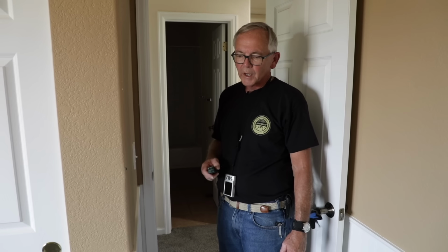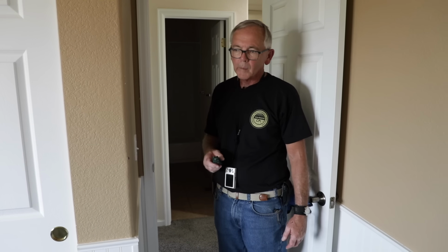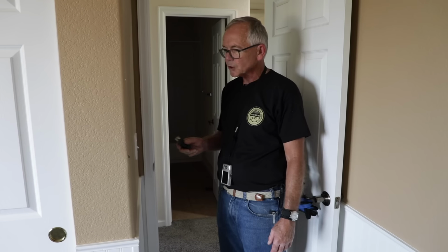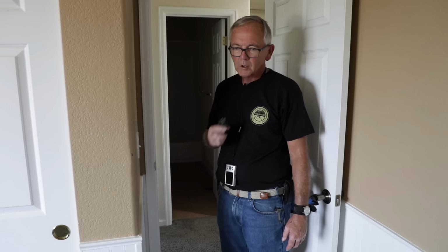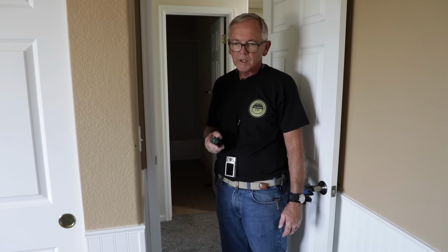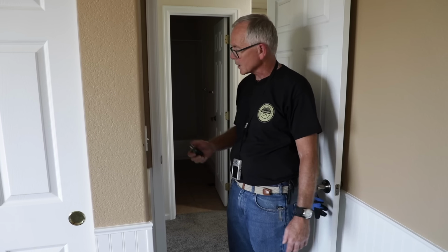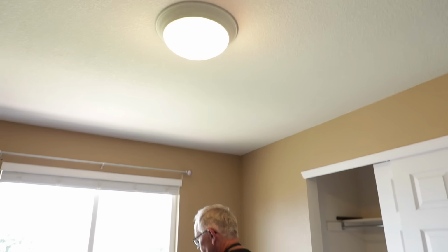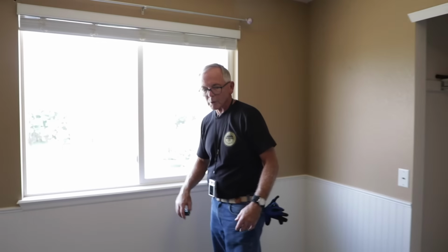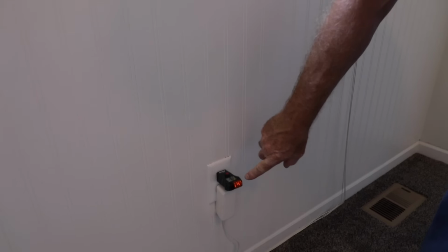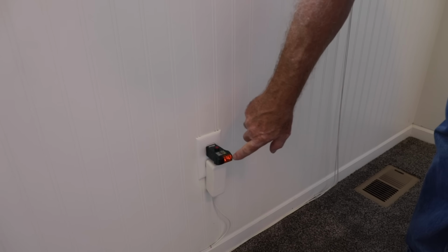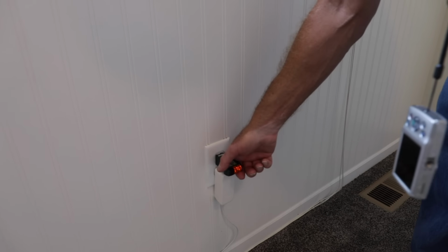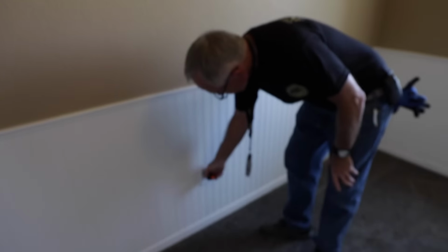Okay, this is part J. We're going to be doing a representative amount of testing of the lights, switches, and receptacles, including the AFCI receptacles, which are in this house or in the basement. So I'm just going to turn this light on, try that. And usually a representative amount of receptacles would be about one or two per room. Plug my meter in. Looking for correct polarity, that's all good there. That one's good. Let's move on to another one.